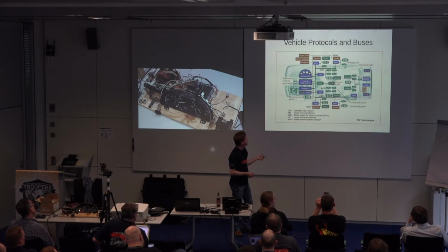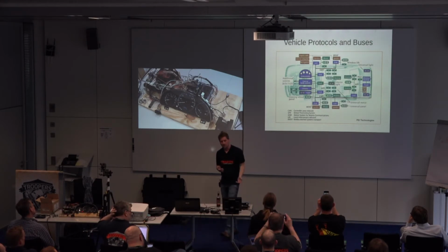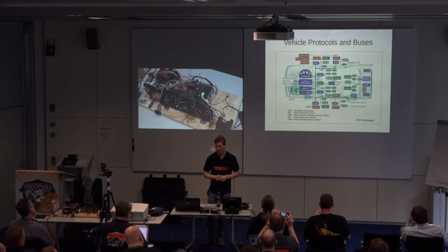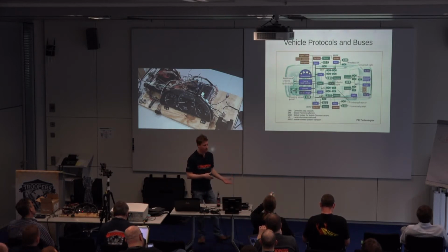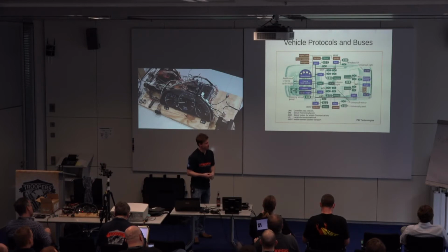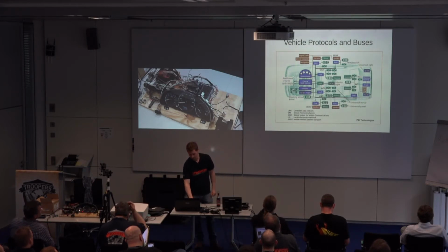Because typically what happens is you're going to have your main brain, your ECU, is the one that controls that LIN. Maybe that's the one that sends the LIN signal down and says warm up the seats. And maybe your infotainment unit isn't on that LIN, you're on CAN. In that case, oftentimes you can tell the ECU on CAN, hey, I want my seat warmed up, and then it sends the message down LIN. It's not really a big restriction, because a lot of times that's where that button is. It's on the infotainment. But it is nice to know about all these different ones.